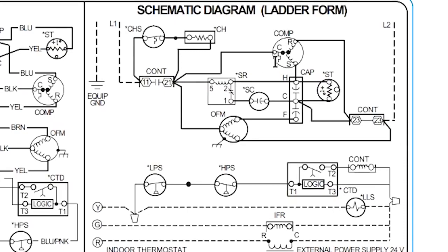You'll notice inside this compressor, there is a normally closed, open on rise thermal switch. Again, you read it like a book. It's kind of hard to see because this is really, really small, but if the temperature were to rise, this switch would open, very much like this one here. You see it's the same sort of symbol. And so that's what a thermal overload is. It's a switch that breaks common. Common is not a winding. Common is just a point in between the windings of run and start, but it's got a thermal overload in there, and that's where you connect L1 in this case. So that shows you how that thermal overload is wired into the circuit.